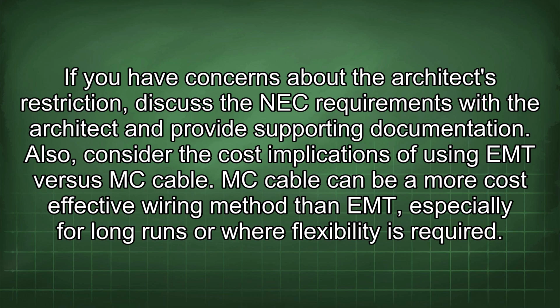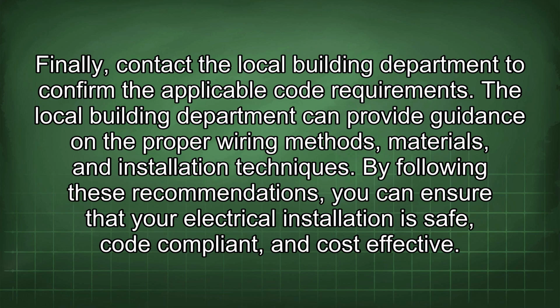Also consider the cost implications of using EMT versus MC cable. MC cable can be a more cost-effective wiring method than EMT, especially for long runs or where flexibility is required. Finally, contact the local building department to confirm the applicable code requirements. The local building department can provide guidance on the proper wiring methods, materials, and installation techniques. By following these recommendations, you can ensure that your electrical installation is safe, code-compliant, and cost-effective.